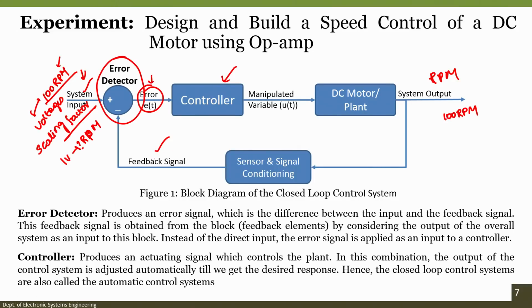The output that we are getting from the sensor should also match with the input scaling factor, which means this particular mapping factor, but we are not very sure whether the sensor can match with this or not. So, first we have to understand how the output of the sensor behaves and how we can map it. By designing a signal conditioning circuit, we have to map the output of the sensor with respect to the input quantity. Then both will be in the same units.